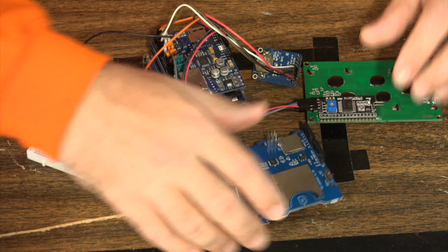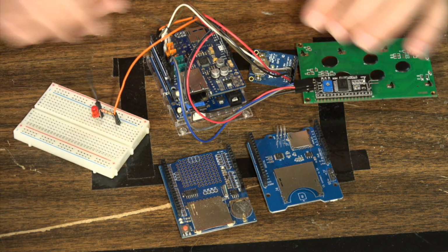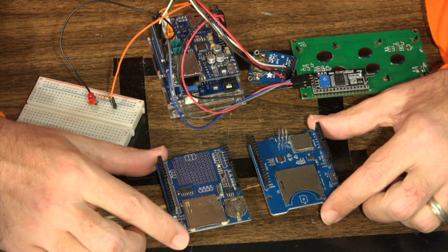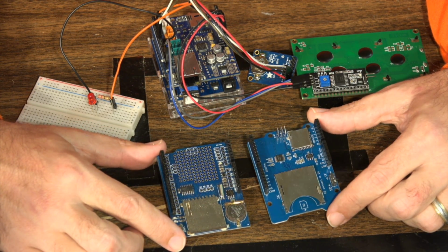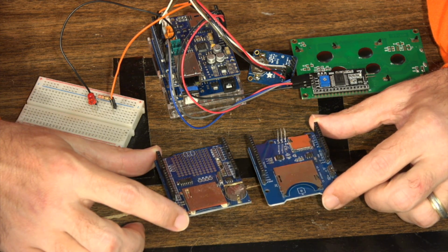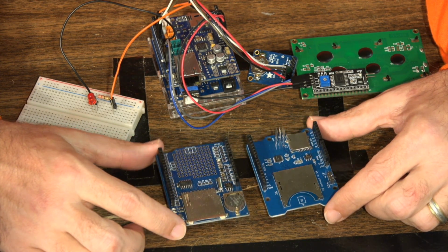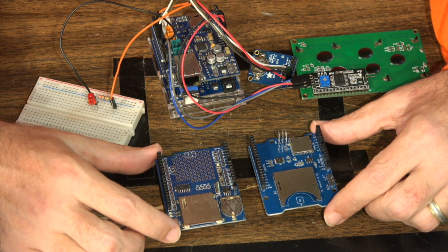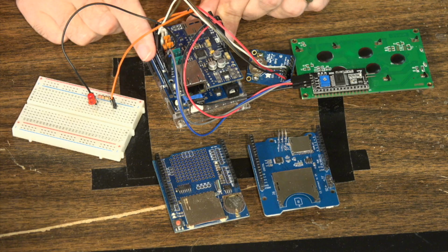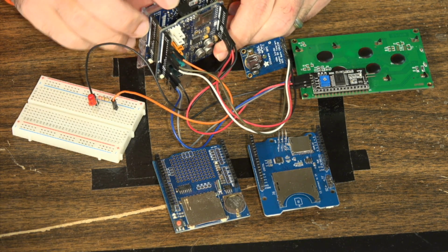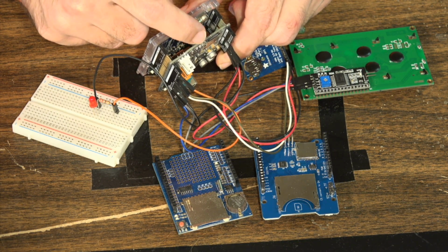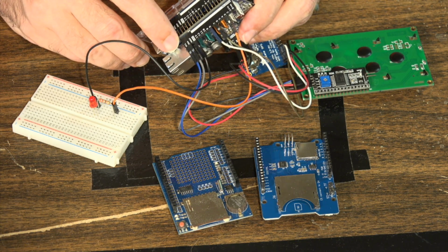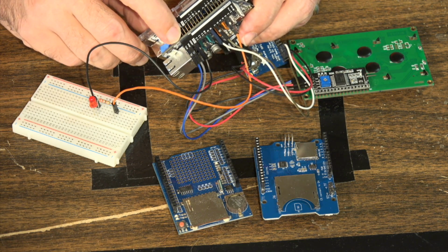Now, I did want to show you some of the other data logging shields that are available and explain why I'm not using either of these 2 data logging shields. So again, one of the problems you run into in the Arduino world is there are 1,000 different products that are 99.9% the same, but they're just slightly different. The big thing with this particular board, why I'm using the Ethernet shield, is it has the ICSP headers. So basically these headers back here, it has the ICSP header connector, and it has the SCL SDA pins that go all the way through.